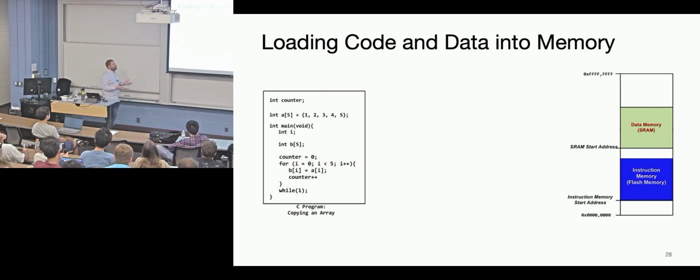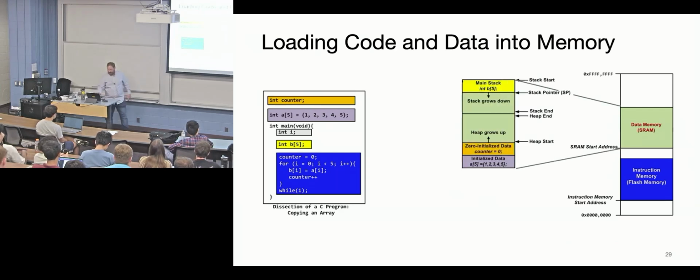It's also useful to think about where your C code gets stored and how it's implemented on the hardware. Here's flash memory, where your instruction space is, and then you have SRAM, where data is. In reality, flash is slower than SRAM, so there's a trade-off in speed. While not important for this slide, in lab you'll find that they take your program out of flash and put it in SRAM when you boot up, as part of your bootloader, just so it can be faster. You do pay some penalty on startup, but for most of your labs it doesn't matter. That's just the default for how Cube IDE runs things.